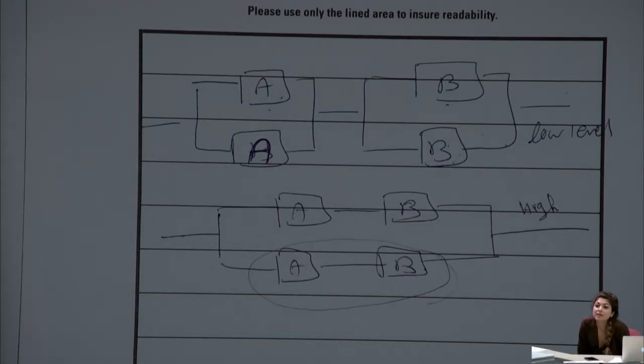Well, you don't have redundancy for the whole engine system, but you have redundancy at the component level. And why don't we have redundancy at the engine level? Weight and cost. There are so many constraints that we cannot consider redundancy at the whole system level. We have no choice but to consider redundancy in the components.